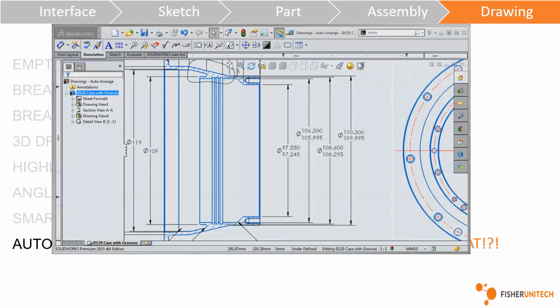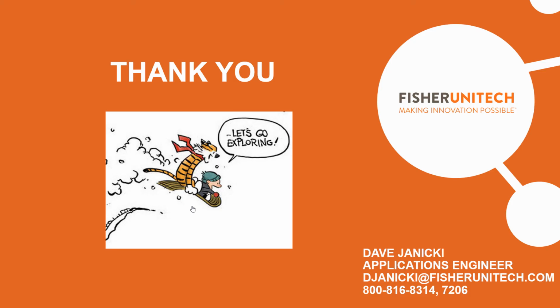Yep. And we'll just fence it in and then cover it. Yep. And then, I mean, we showed you that select all earlier. This is a lot of times where that select all is most used. So if I select one dimension and do Control A, it's going to give me all the dimensions in that drawing. And then I can auto arrange them if I want to. That's a good example of where that's actually used. So that's what I have for you today.